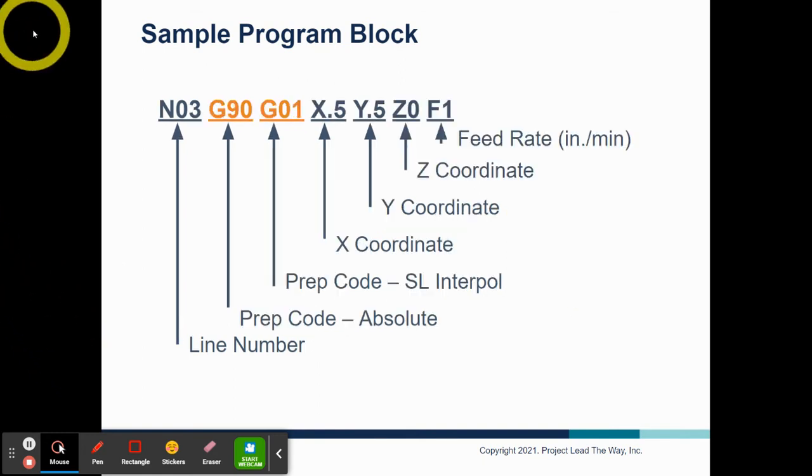And then this is when it gets a little more complex. This is actually line number 3, so the third line in a code. This third line has a lot more call outs. You'll see these G codes now. This is the first time that we see G code. The first one here is G90. What G90 means is that you are setting your machine to absolute coordinates.